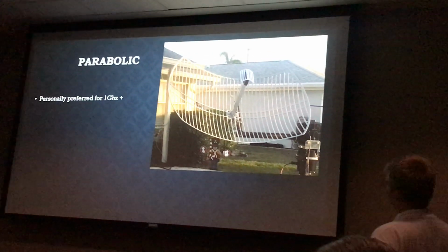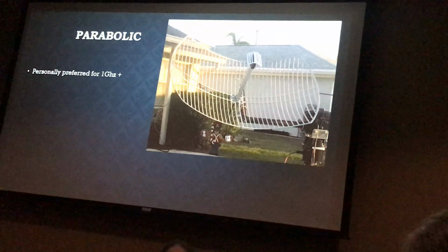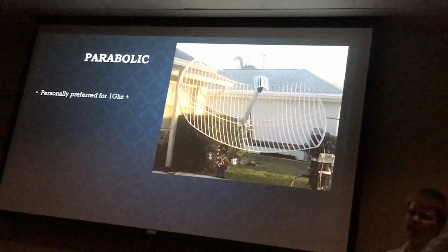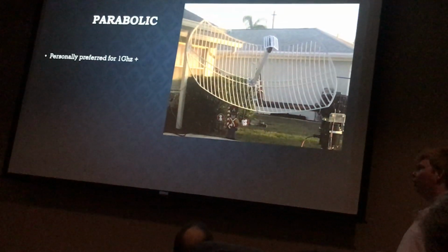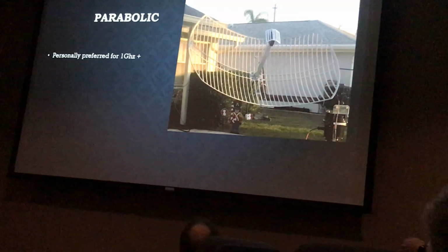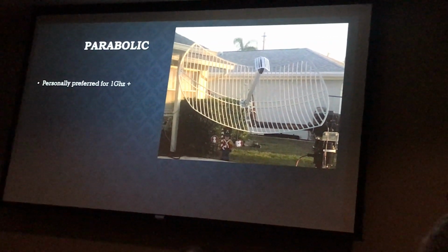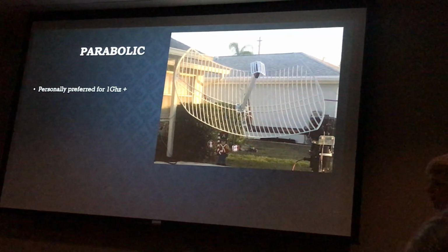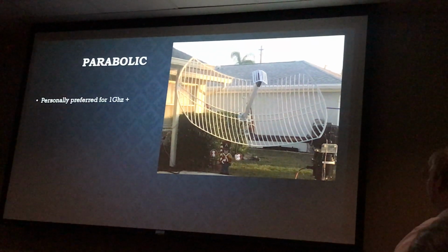I was thinking, now there's some open source LTE software becoming available. So one thought I've had is that being able to operate an amateur-owned LTE network would be pretty cool. One of the problems is that LTE is built around encryption. So there's two ways I could think of to get around that: either have a straight zero encryption key and publish the encryption keys to get around the FCC guidelines, or figure out a way to disable the encryption altogether.